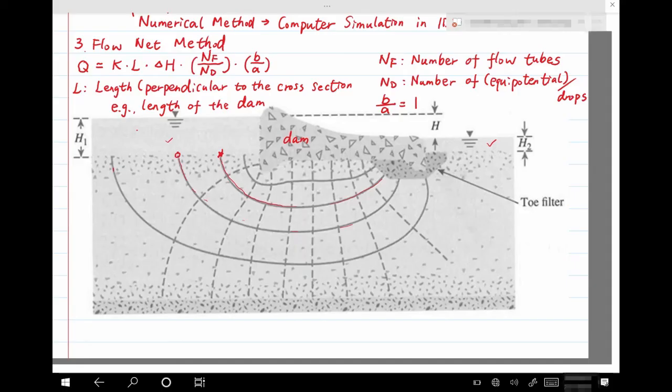In the demonstration, you see these different purple lines. They were created because the guy put some dye at different locations on the right-hand side of this glass tank. If water moves, water will carry the dye as it moves, and that will form those purple lines. These purple lines show the path of the water movement. It's actually one set of lines in our flow net. It's called a flow line. Let's jump back to our notes.